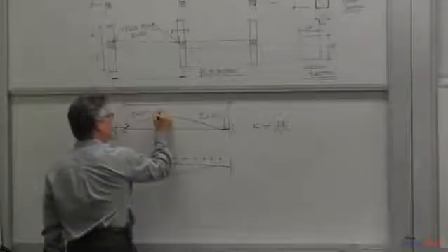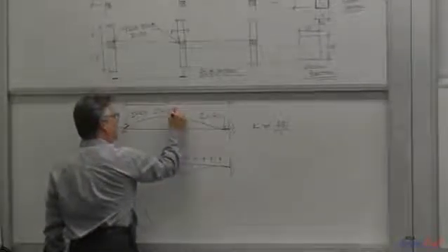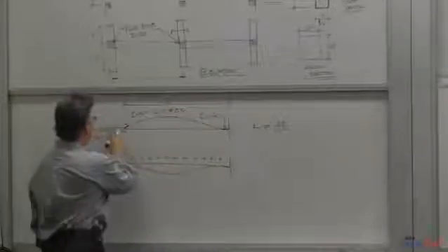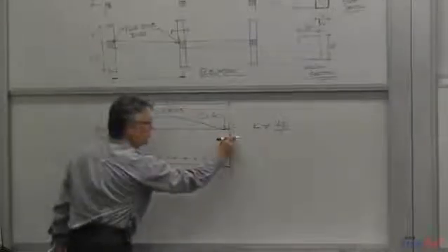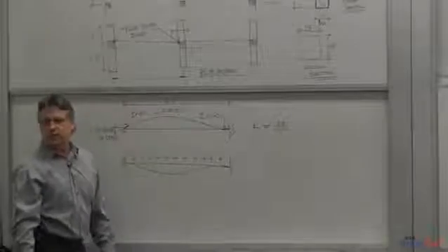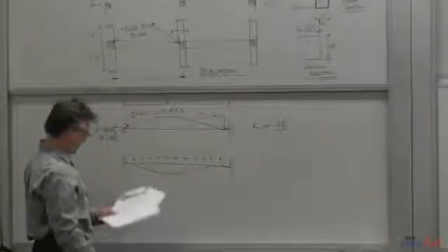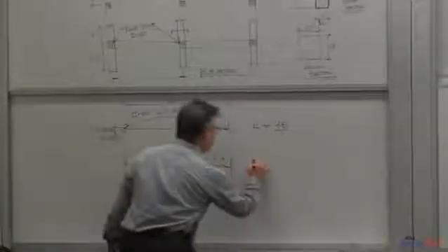And that means that the carryover factor is not equal to 0.5. When I put a moment on here, I don't get exactly half that moment over here. So nothing that we've been doing applies anymore.